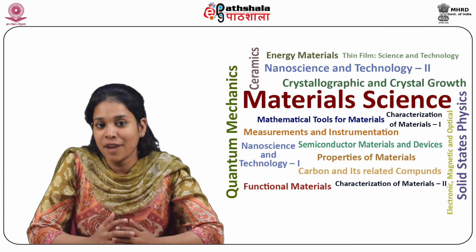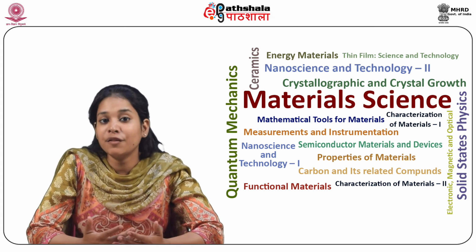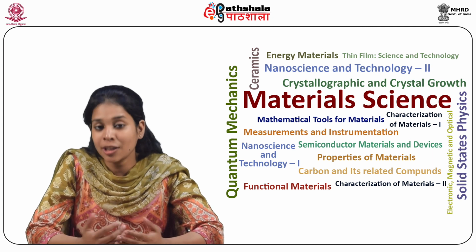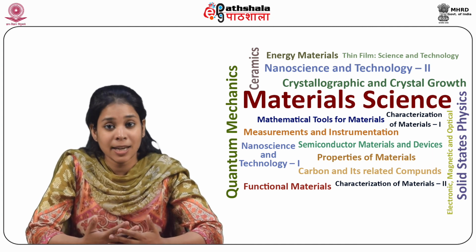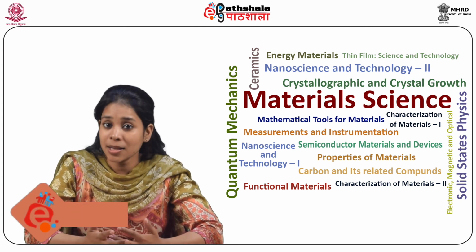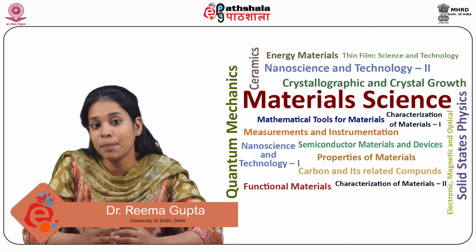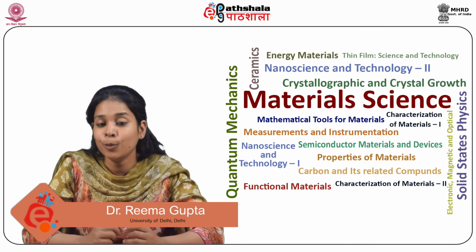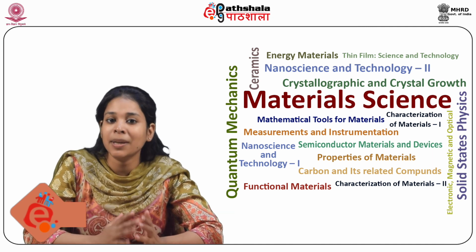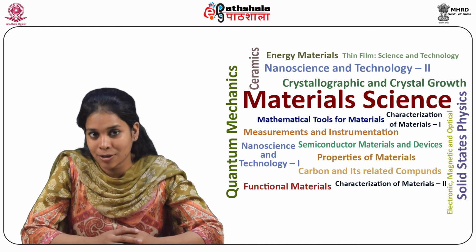So the disadvantages of liquid phase sintering are, liquid phase sintering may not be suitable for those applications where the components need strength at very high temperatures, as the glass phase at the grain boundaries softens at higher temperatures. Also, the presence of a second phase may degrade mechanical and other properties even at lower temperatures.